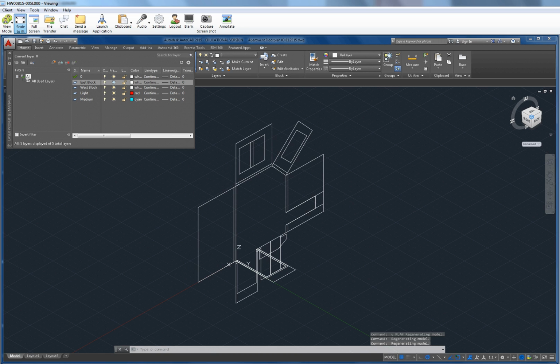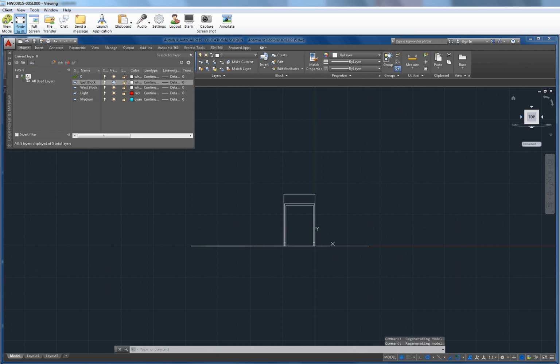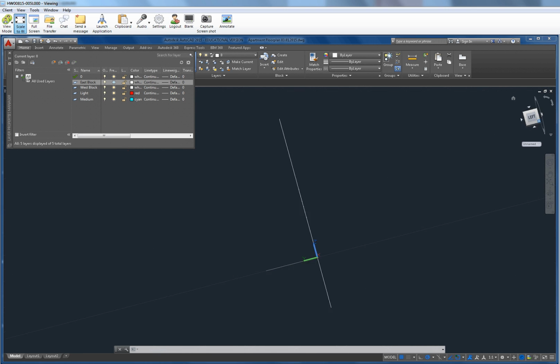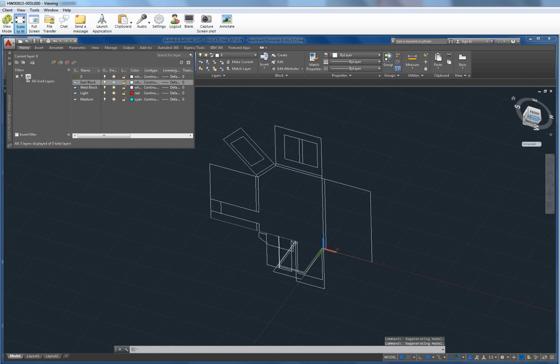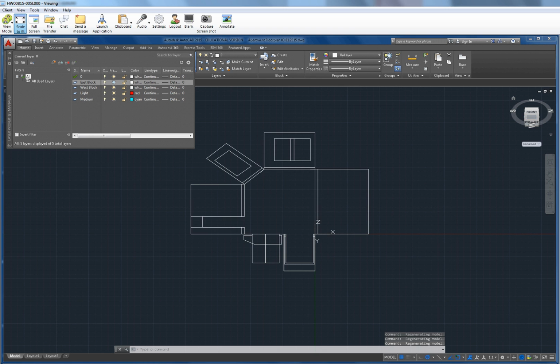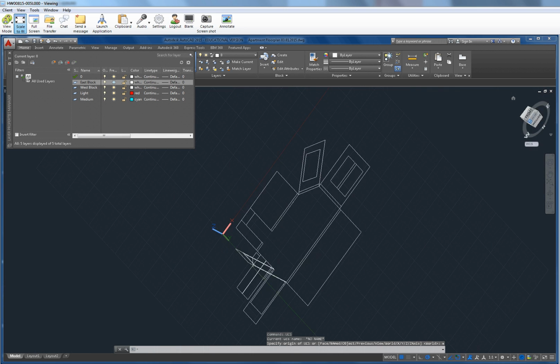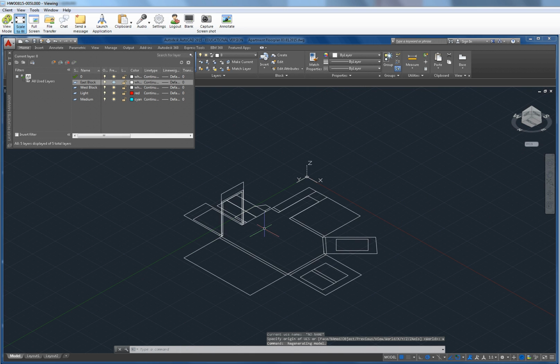Yeah, because when you're looking top down, you get the rotation little arrows on the view cube. So you could rotate it 90 degrees, but once you go to the isometric view, it takes away the arrows, so you can't do that. And when you think you're getting what you should be getting, you don't quite get it. So it becomes awkward to start the maneuver. So unfortunately, it's going back to world, getting the view you want, and then getting your UCS where it needs to be.